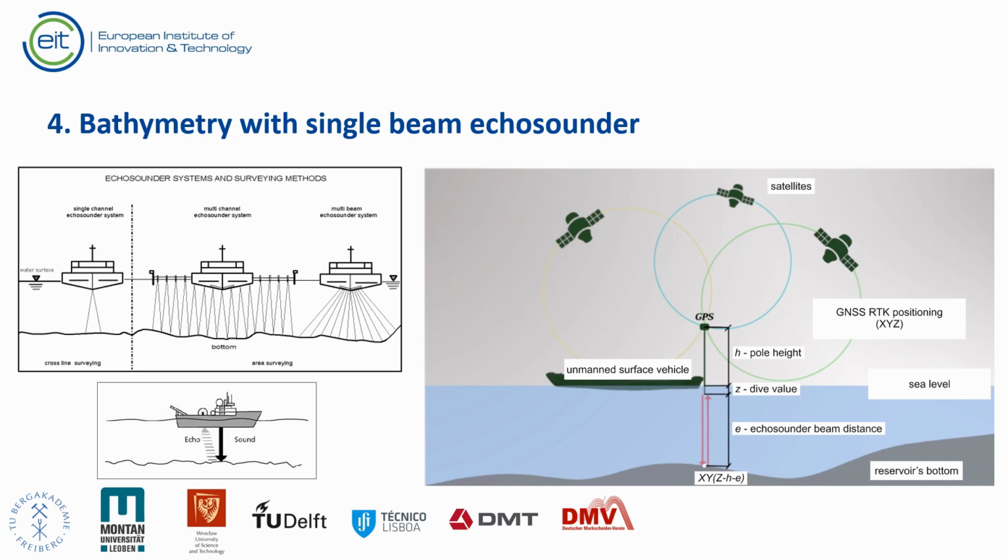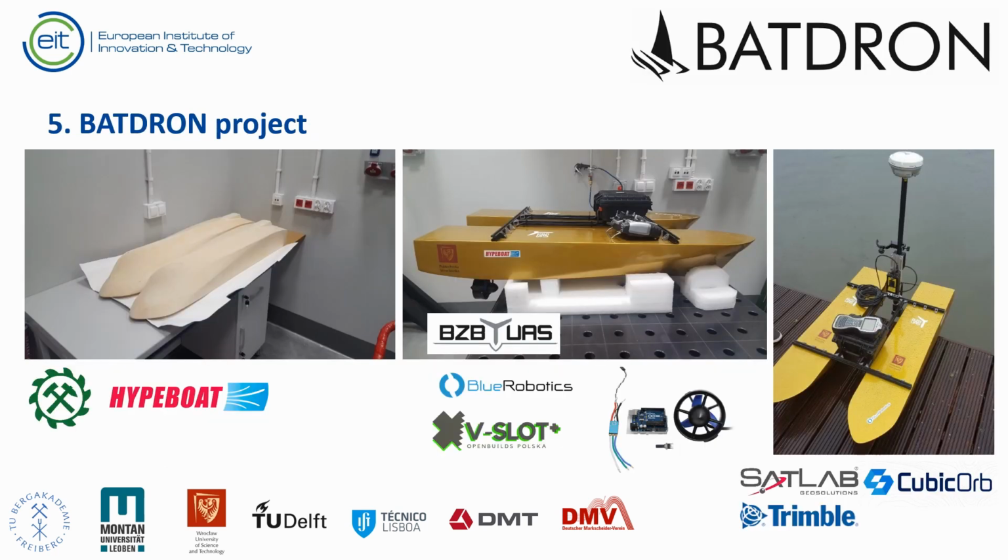Single-beam echo-sounders, which can be used here, are small devices that usually do not require motion reference units, MRU, to determine the spatial orientation. Hence, they can be mounted on smaller vessels, whereas multi-beam echo-sounders are placed on larger survey vessels. Members of a young surveyors scientific group were able to build the USV with low-cost components, including Blue Robotics thrusters and enclosures, a remote control radio, and a catamaran hull. The catamaran hull was milled on a 5-axis CNC milling machine by Hyperboat.